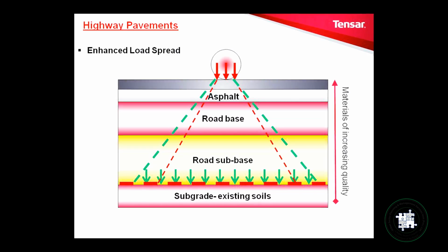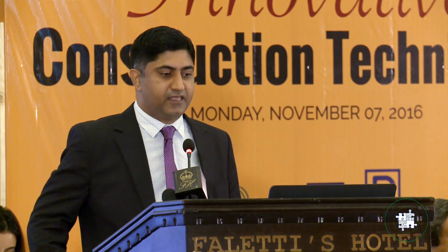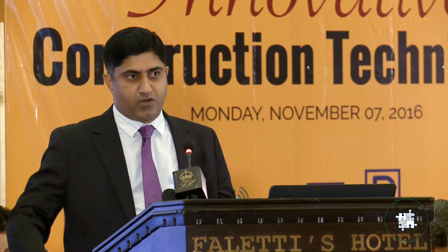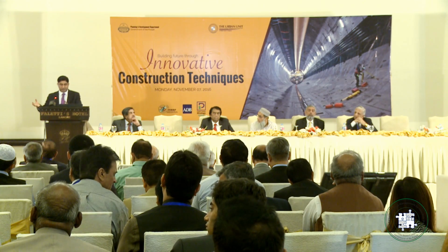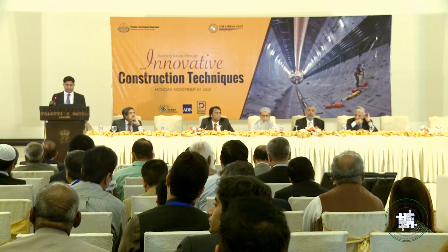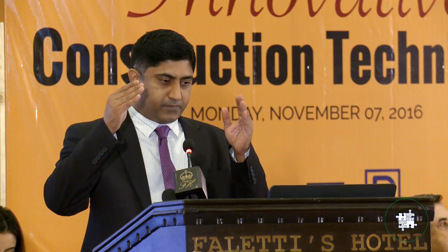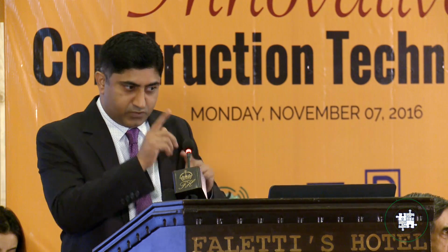The wheel passes again and applies pressure, but this time the load distribution is a lot wider, which means the stresses at the top of the subgrade are now reduced, because the load is the same and the area is more, so we get reduced stresses. These reduced stresses protect the subgrade, so there is no deformation in the subgrade. We remember the original was causing a punching type of failure, while the wider area does not cause a punching type of failure. So this is, again, the concept.